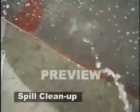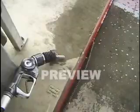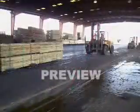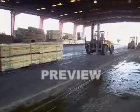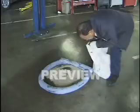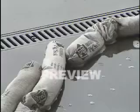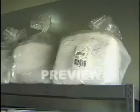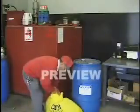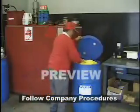Spill cleanup. It is the vapors rather than the liquid itself that burn. When the liquid is spilled, vapor release begins immediately and continues until the liquid is removed. This requires that cleanup operations begin at once. Specially developed absorbent materials are offered in pillows, pads, sheets, tubes, and other shapes to fit all cleanup needs. Once the absorbent material is saturated, it should be placed in a large disposal drum and sealed with a drum cover.